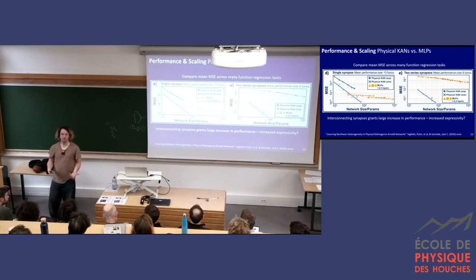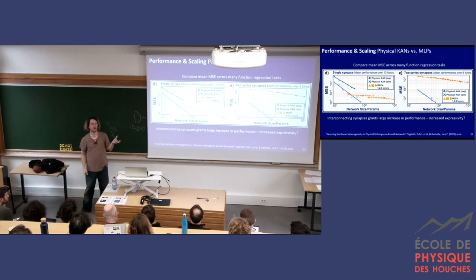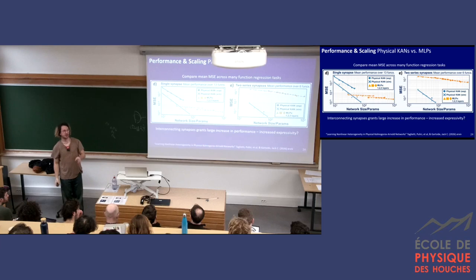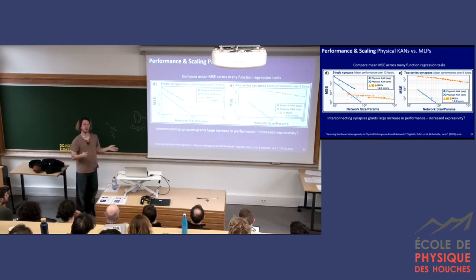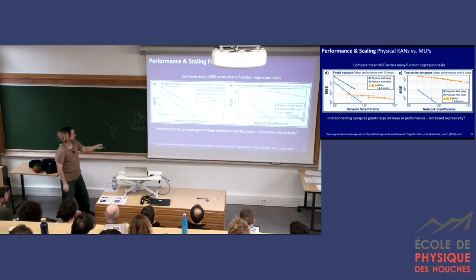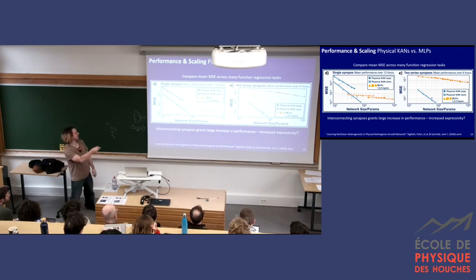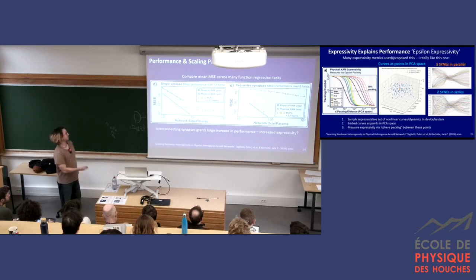But then we thought, okay, one of our synapses doesn't just have to be these devices in parallel. What if we interconnect them? So what we've done over here is just stuck the 2 in series, and here we really get a boost in our expressivity. So even though your noise goes up, so even though it's time multiplexed, all of the experimental noise is real. The only thing we're doing off chip is linearly summing these things back together. We can really outperform by a nice margin the MLPs, and we get a better scaling. So this was interesting, and I wanted to kind of unblack box it a little bit.